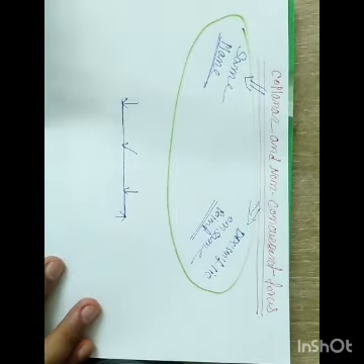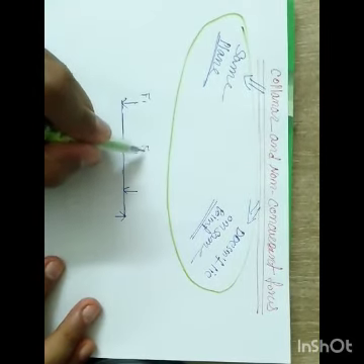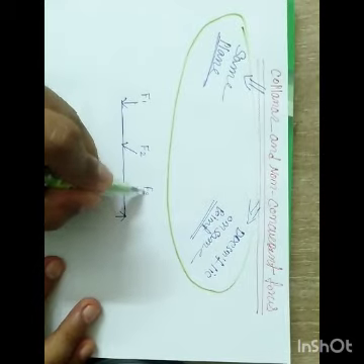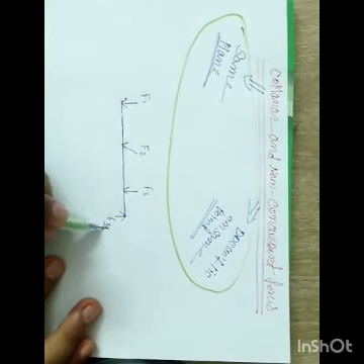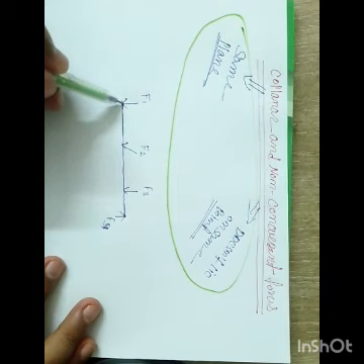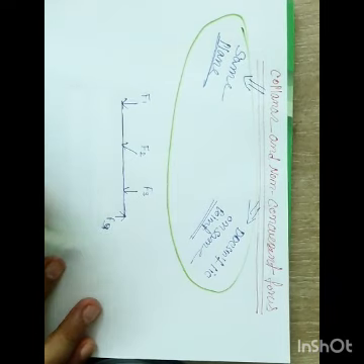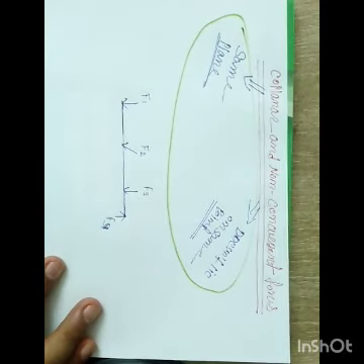So you have four forces, F1, F2, F3 and F4. These four forces all lie on the same plane, which is the rod, but F1, F2, F3 and F4 are not on the same point. So this is an example of coplanar and non-concurrent forces.